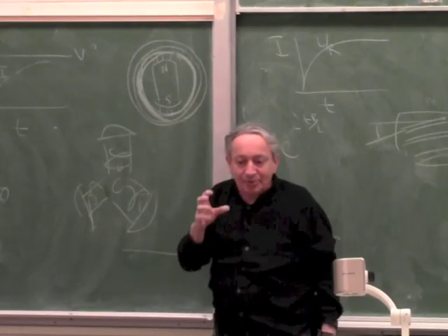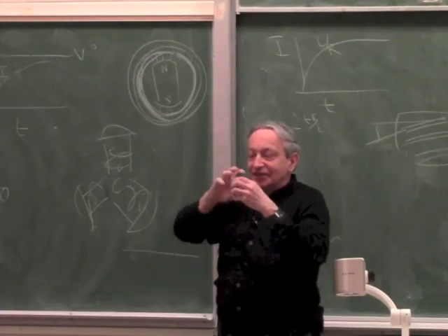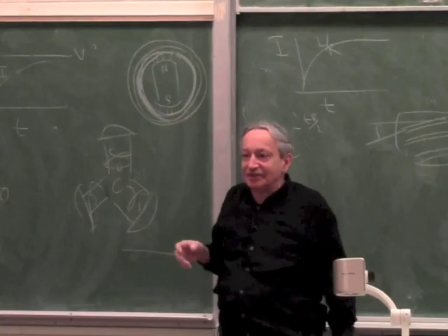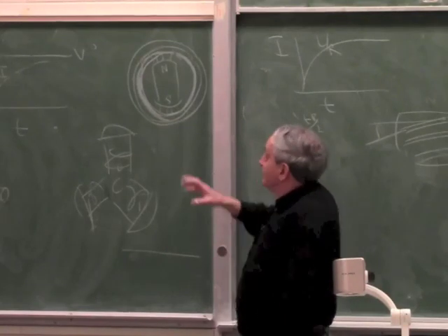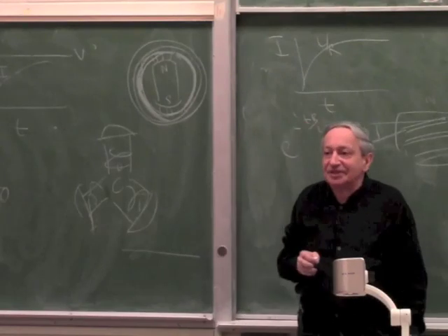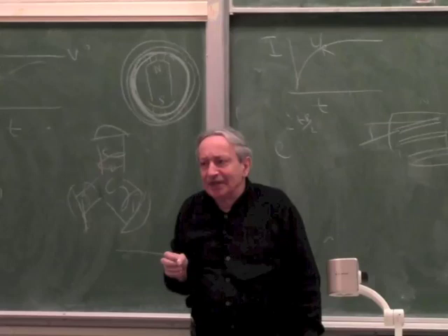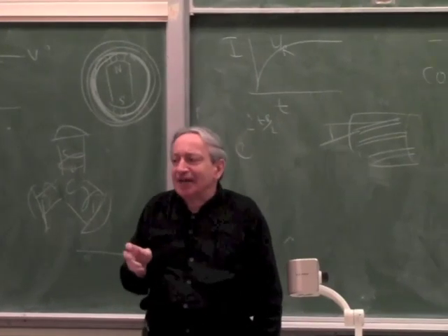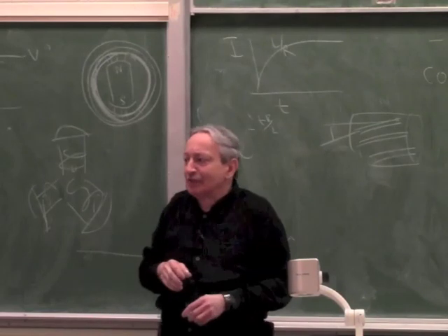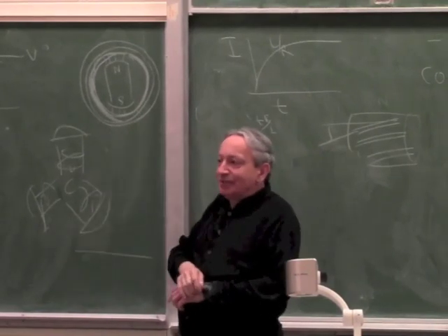Okay, is that clear? So is the geometry clear? Imagine a teacup that has a magnet on the inside, a ring of steel on the outside, and the teacup can rotate in between, but the teacup is made of winding. So this is the most popular construction for a high-performance DC servo motor. For example, the motors made by Portescap, or all the standard names of when you buy a high-performance DC servo motors are all a bit like this.